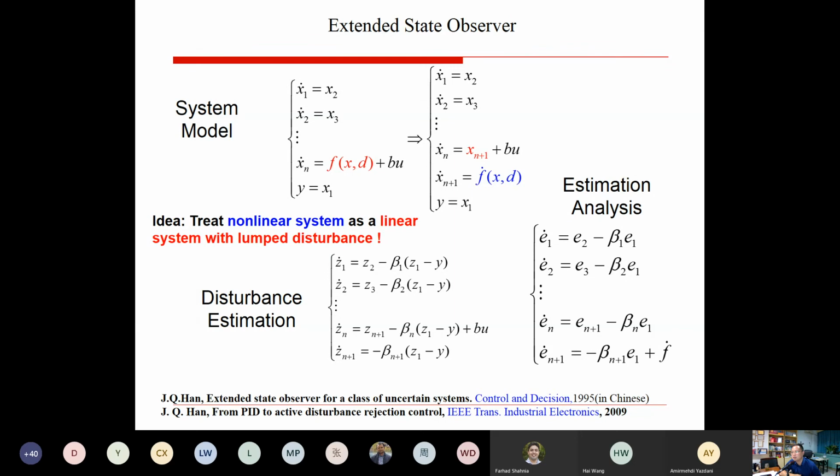So in this case, if the saturation has a big influence on the closed-loop system, maybe we can suggest that the designer, in the next cycle of the whole system design, should add control energy. You should add hardware output. You should add control torque.